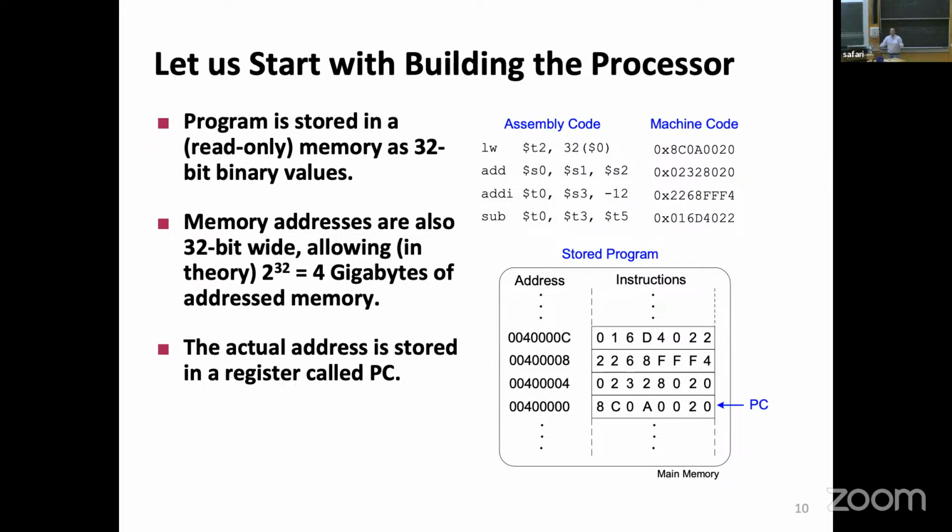16 bits. How many bits do I need for the ALU? I need 32 bits. So what happens is I have to take this number and extend it. And of course, this was the yellow part. So this was 16 bits that I stole from instruction 15 to 0. And I blow it up to 32 bits.